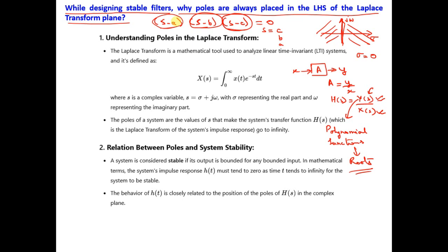Now at these locations, wherever the solutions are, say for example, if you are considering the solutions of Y(s), how will it affect the transfer function? Directly. That means at those particular points where you have the solutions, the value will become 0. So these solutions exist on the Laplace plane, and since they are present on the Laplace plane, at those points you will have an amplitude of 0.